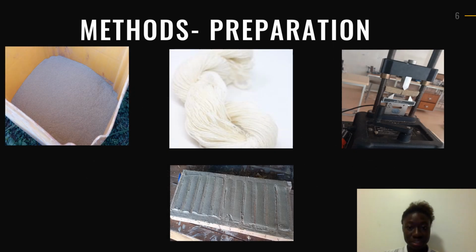Clay ores were physically pounded and sieved into powder, and then the clay was reinforced with fiber. The fiber was cut between 2 centimeters and 3 centimeters long. Only clay was casted as the control experiment, but the samples itself were 60% clay and 40% fiber. This was volume proportion. Also, when water was added to the clay only and the fiber and clay mixture, this was cold worked for 3 days before being casted.